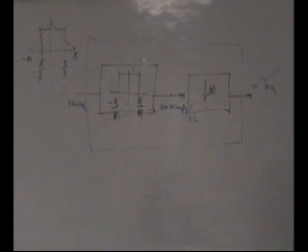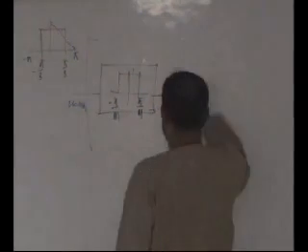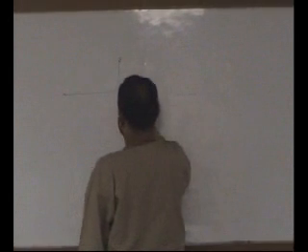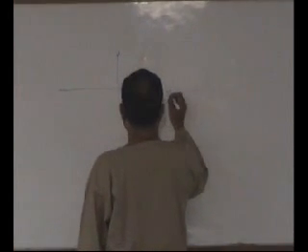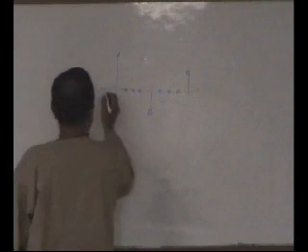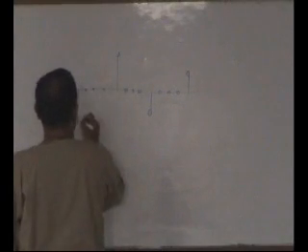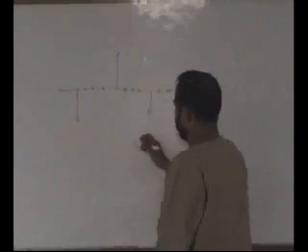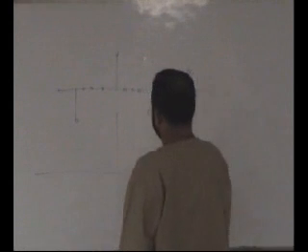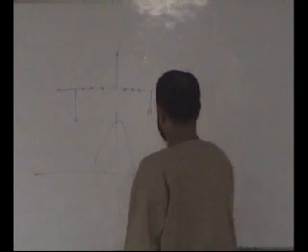Similarly, the same is the case in interpolation. In interpolation, first you insert zeros. Once you have all these zeros, you have this value, then zeros, then this value, then zeros, then this value. So you are convolving this signal with a sinc, which is something like this.